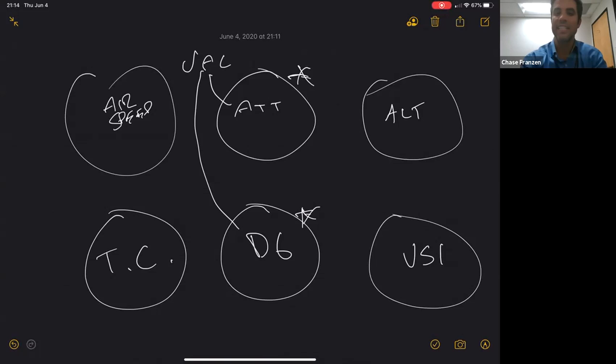So what's happening is, in the attitude indicator here, I keep wanting to draw on this screen, but I'm actually down here. There is a gyroscope that is spinning horizontally inside of the attitude indicator, just like what I just drew. So that gyro is resistant to motion as our airplane banks left and right. That gyro wants to maintain level with the horizon. That gyro is level with the ground, sort of.